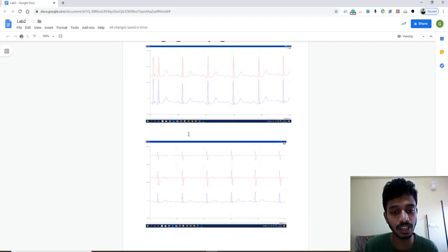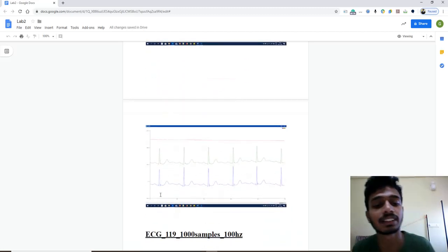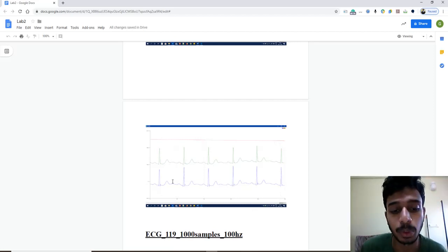So this is peak detection in the ECG signal, which is obtained by passing the ECG signal through a moving average filter followed by a derivative filter of order 1 and 3-point central difference. So this is baseline drift extraction. As you can see here, blue is my input waveform, red is my baseline drift component, and green is the signal free from baseline drift component. As you can see, even here the baseline drift component is almost a straight line, indicating that my recorded input is decent enough and free from baseline drift component.